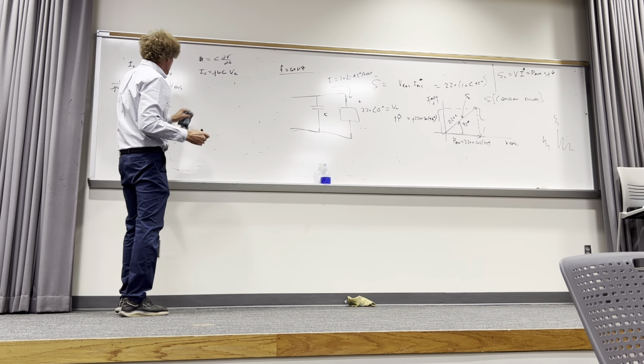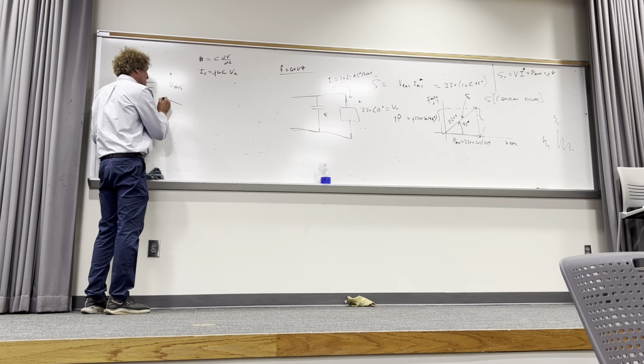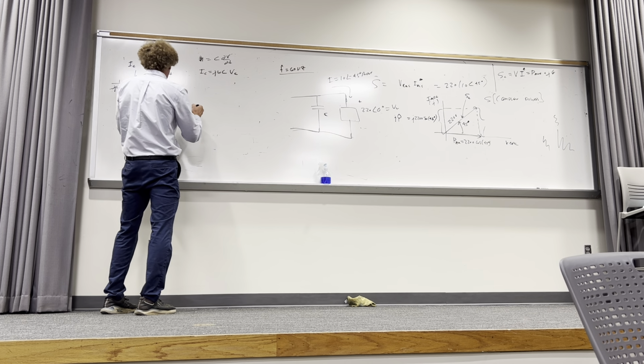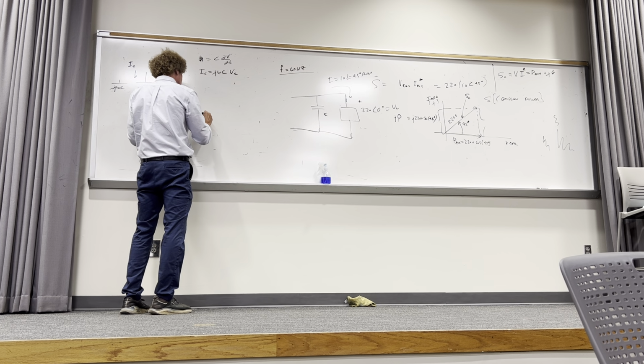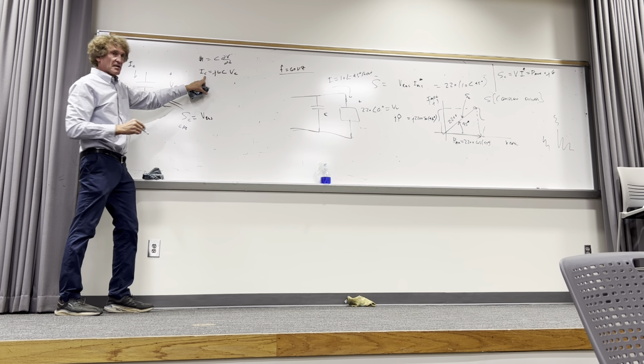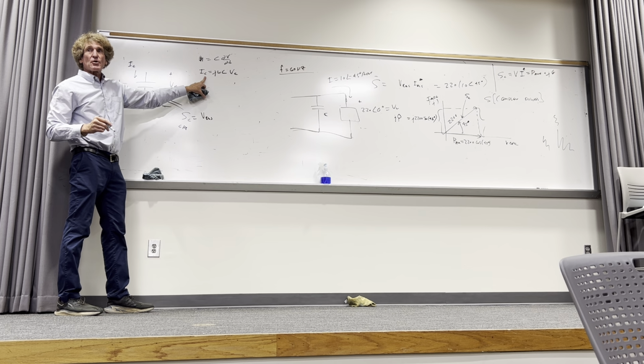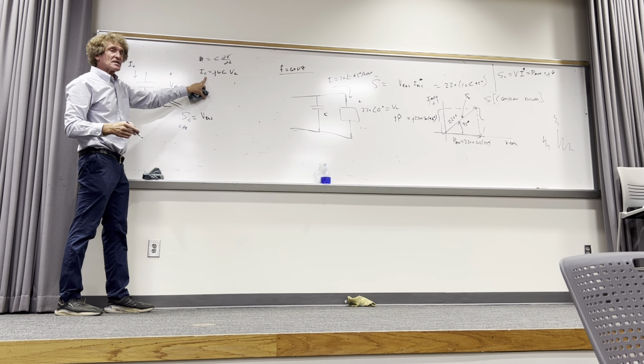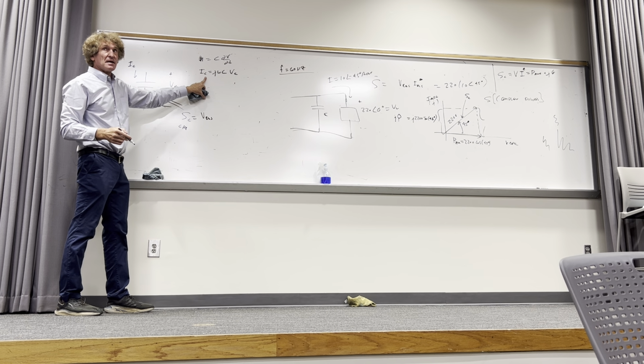So with that in mind, this capacitor right here has a complex power, and this is only for the capacitor, of VRMS, we'll just assume it's VRMS at 0 degrees, times I RMS conjugate, right? You all see how that would be the current through the capacitor. Can you see it in the far back, by the way? Back there, guys? So conjugation does what to this? Class? What happens to the J? Minus J. You all with me?